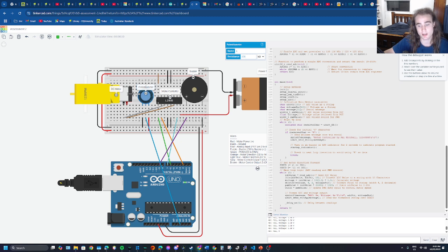We set it to about half, it ends up showing 2.5 volts and it goes down to half the RPM. Set it to 0 RPM. Set it max again, it becomes 243 RPM, and the voltage in the serial monitor is showing 5, ADC value 1023. As you can see, the RPM scales based on the voltage, and that is my solution.